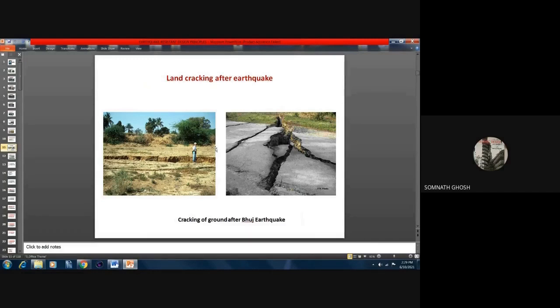It was a job of 300 crore, and there were 250 structures, and we had to classify these structures depending on damage level. Some structures we recommended to demolish because you can't really go for retrofitting. It will be huge cost. Some are retrofitted, and for some minor repair was sufficient. So there were 250 structures, and I was the consultant in that project.